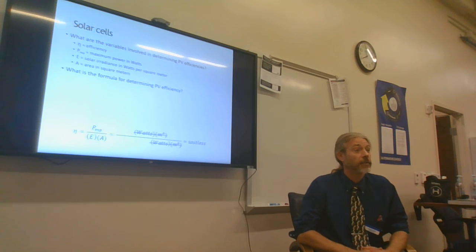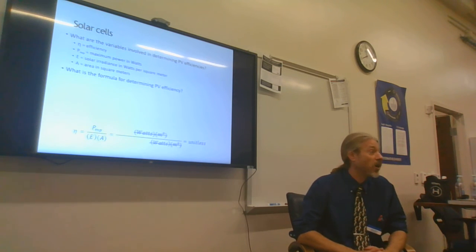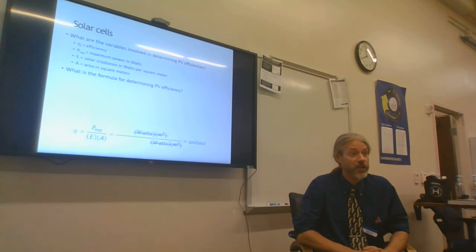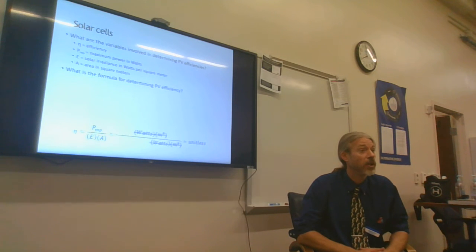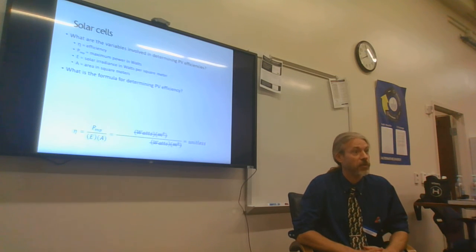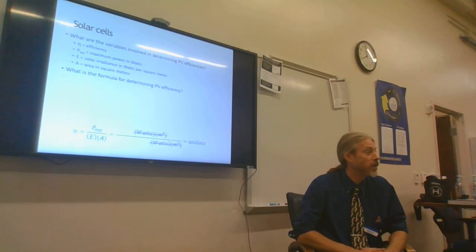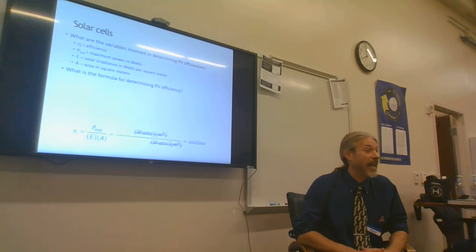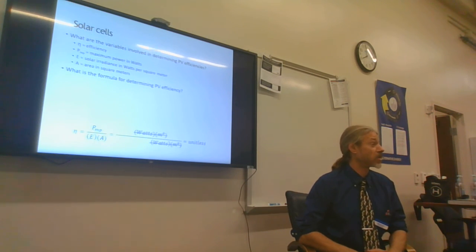1,000. So I'd take 10 square meters times 1,000 watts per square meter times whatever the cell efficiency is, 22%, so times 0.22. So 10 times 1,000 equals 10,000 times 22% efficient would be 2,200 watts of solar panels that you could put onto that roof. That's a really, really quick way of being able to tell how much solar panels can I get on this customer's roof.